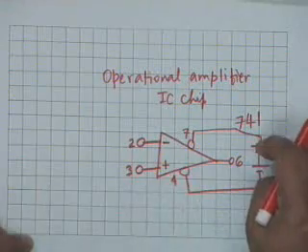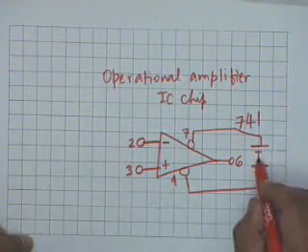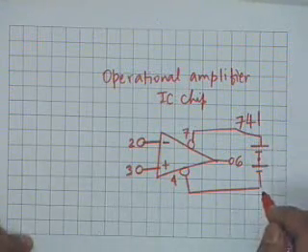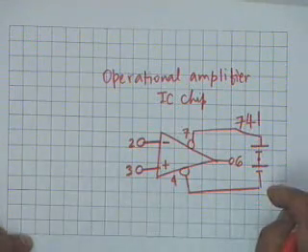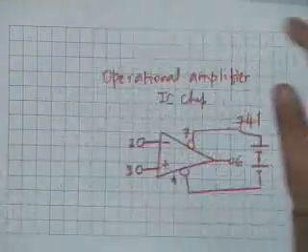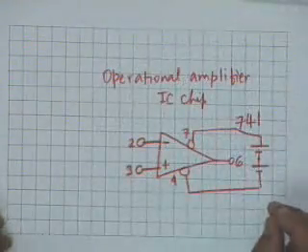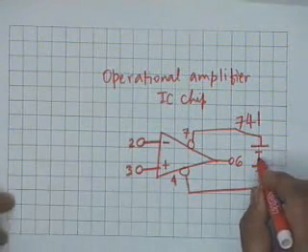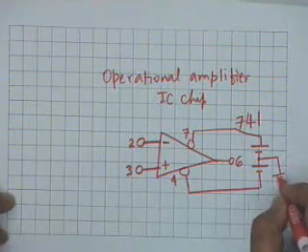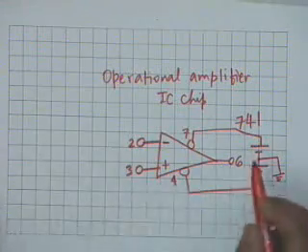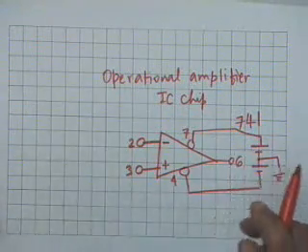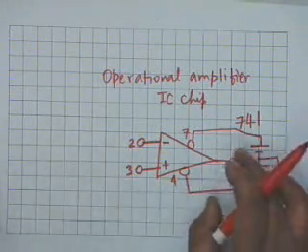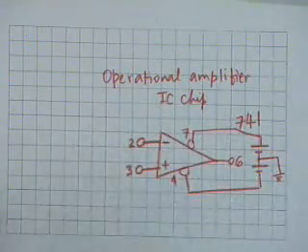Typically this could be plus 12 and minus 12 volt, and the middle point of this power supply, you understand what this is? I am showing this as a series of batteries. This is actually a rectified AC which is available in the laboratory in the form of a box, and it is called power supply. All that it supplies is DC. Typically it could be plus 12 and minus 12. The middle point of the supply is the reference potential and is connected to ground. All right. As far as amplifier characterization is concerned, 4 and 7 do not come into the picture. 4 and 7 have to be connected to a battery, otherwise the circuit does not work.